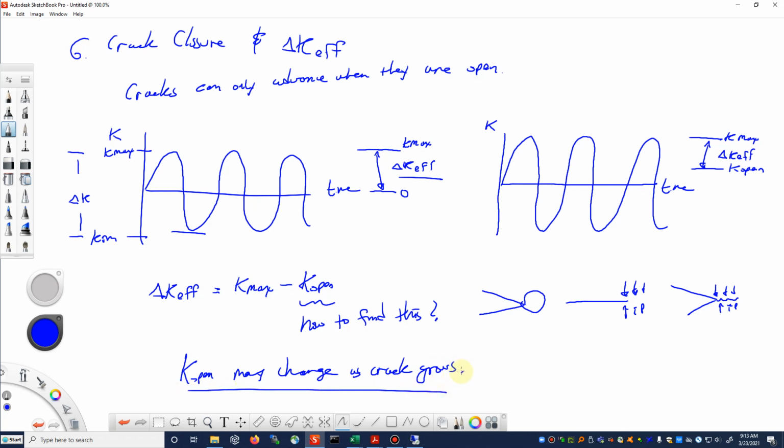Okay, so again, this is just one of these tricky things about fatigue crack growth, when that is important. So take a look. Maybe a safe estimate here would be to use 0 to maximum as a stress intensity factor range. You usually don't get into too much trouble when you overestimate the loads. When you underestimate the loads and stress intensities, then you can be non-conservative on your life estimates.